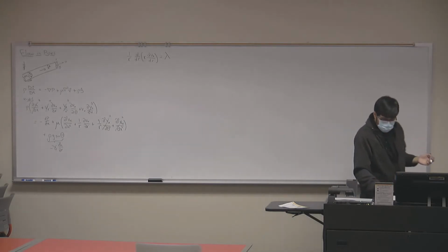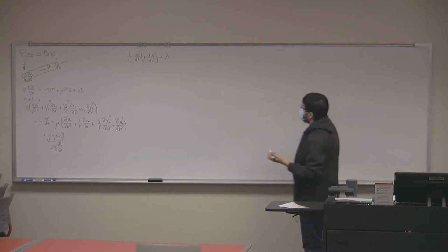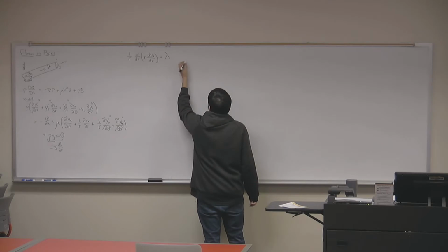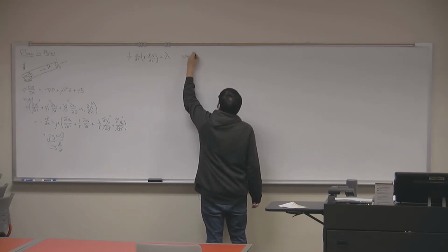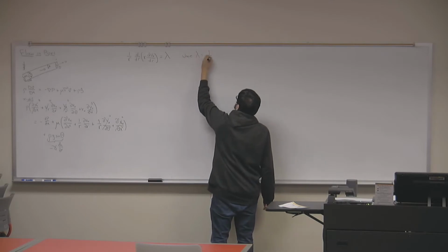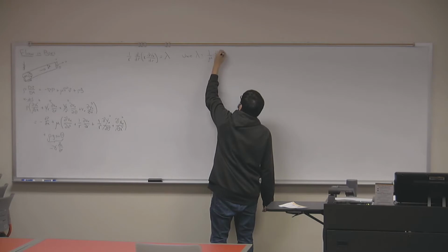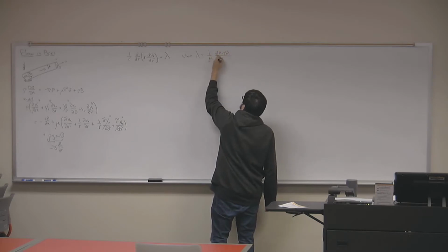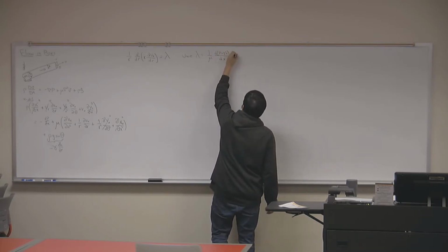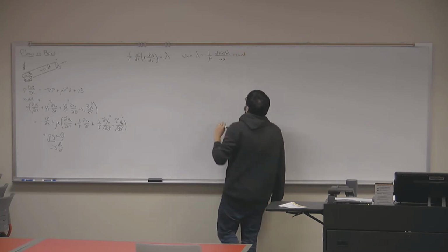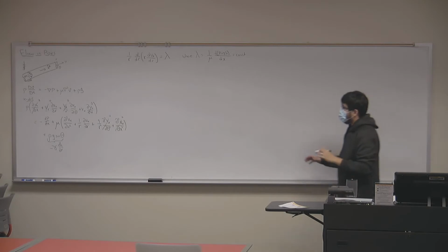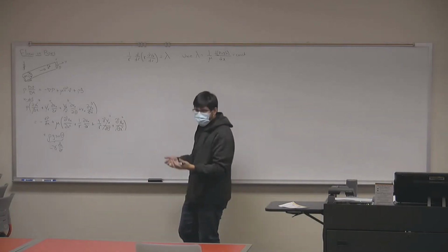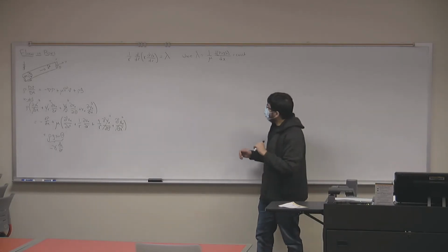In this case, the constant lambda was the same constant that we found for our flow between parallel plates. So we got this equation where lambda was equal to 1 over viscosity times d of pressure plus gamma h over dx, which is a constant. Okay, so that's where we left off in our last class. Again, if you want to know how we go from here to here, you can look at the last class. I think the steps were pretty detailed.